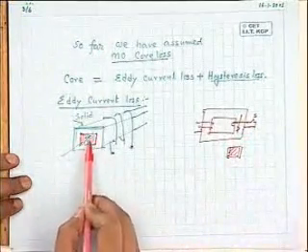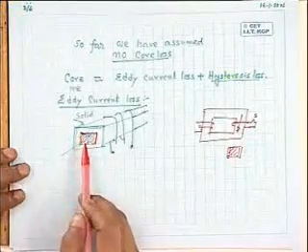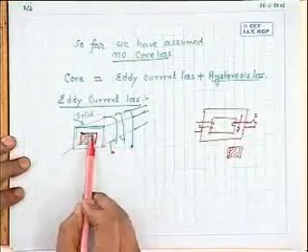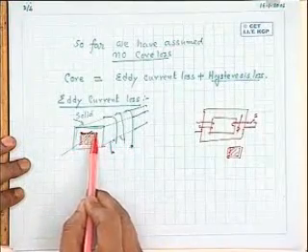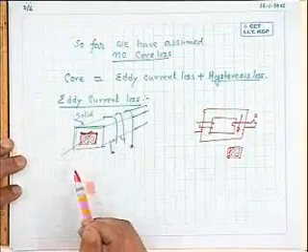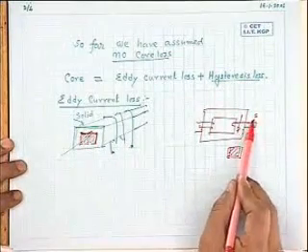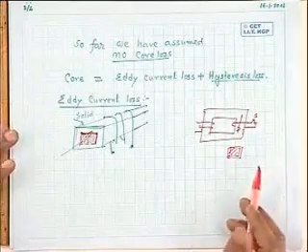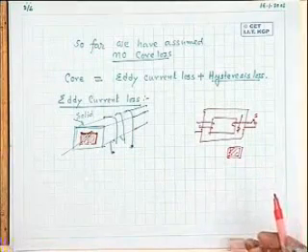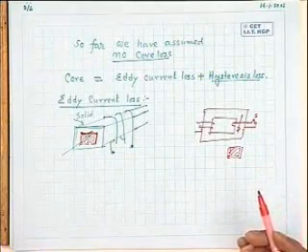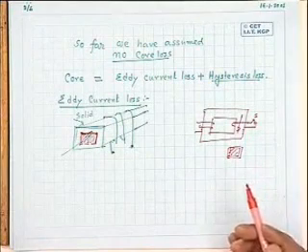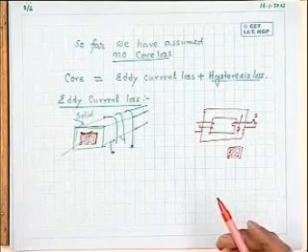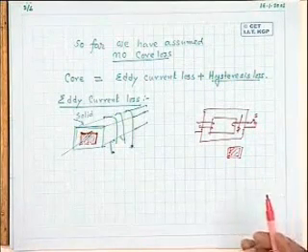Now, in this particular case, it so happens that this imaginary coil is already closed by a switch, because iron is a conducting material. You don't have any control over it. That is, the situation is as if there are already some secondaries present which are closed onto themselves, so there is some induced voltage and the circuit is completed, something like secondaries of a transformer already loaded.